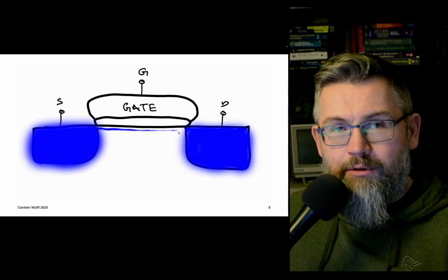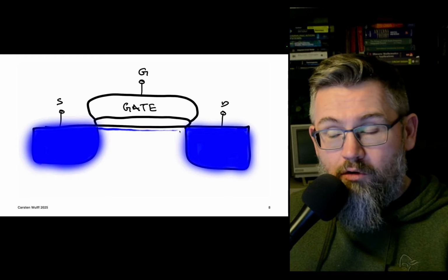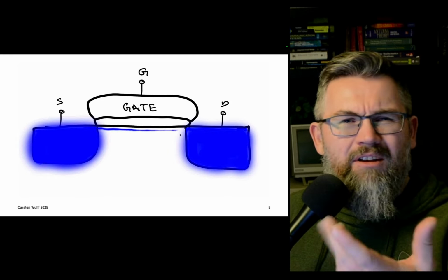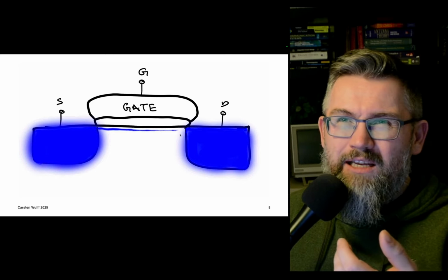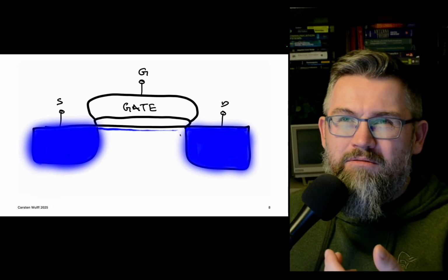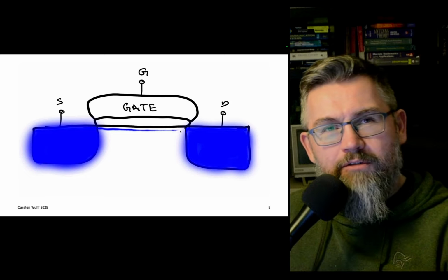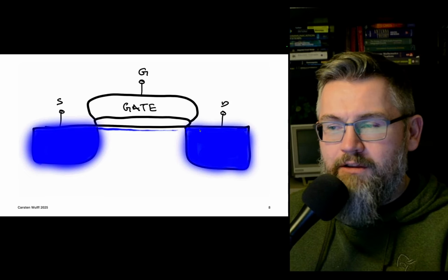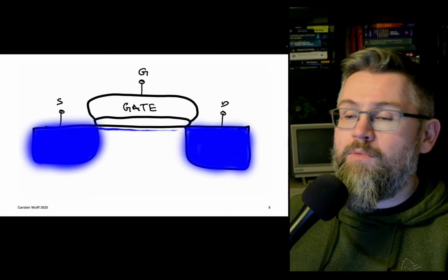It disconnects from the drain, and there will still be a current that can flow, because now we have a depletion region, or basically a region kind of like an insulator, where the electrons, well, it's not like an insulator, because the electrons can still move if they get into that region, because there's a very strong field between the end of this blue section and the drain section. So they sort of get swept across if they get into that region.